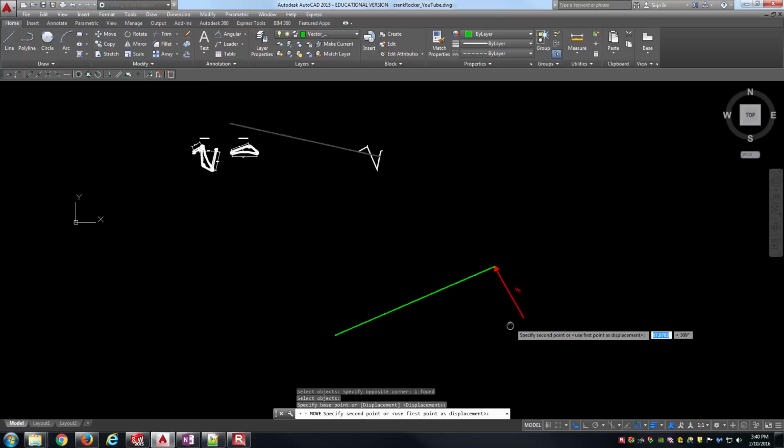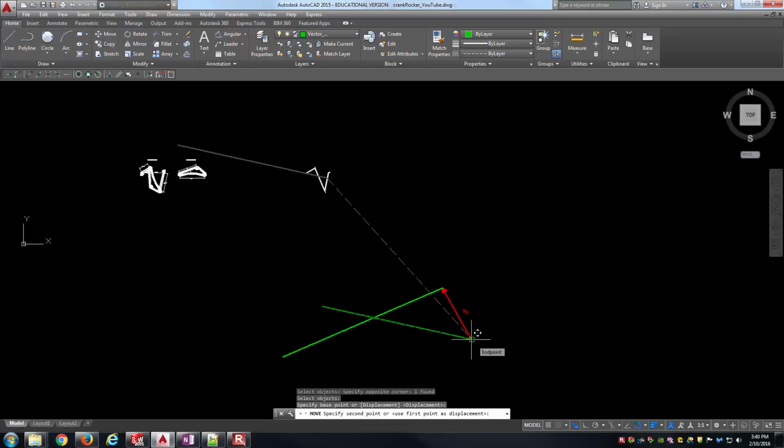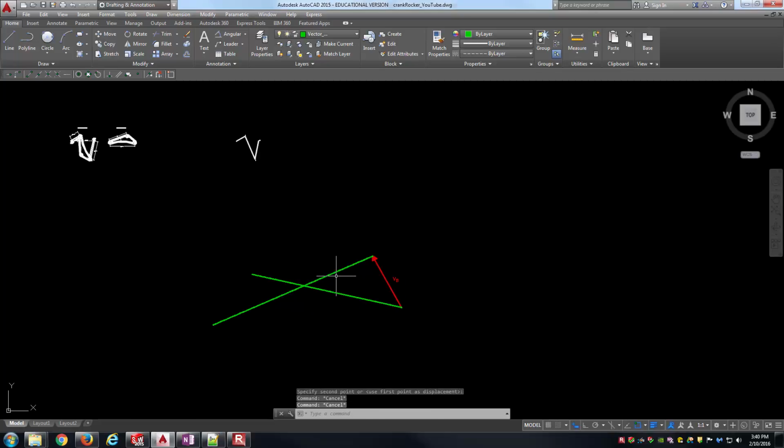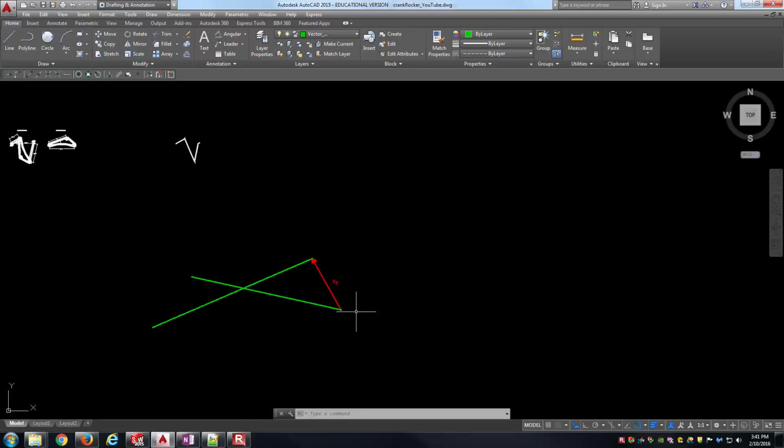And so when I move it here, I'm moving it to the endpoint, you can see, of the first vector I drew, the red v sub b. And really, by looking at the intersection, I'm looking at the solution to that vector equation. One thing to note here, I did assume the right directions for both of these. That's why they intersected here. But if you happen to not assume the correct direction, basically you'll end up with something that keeps extending off and not ever meeting together.